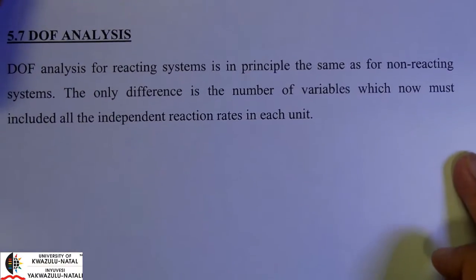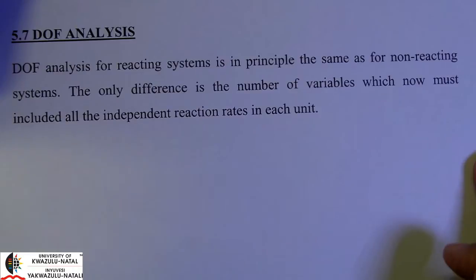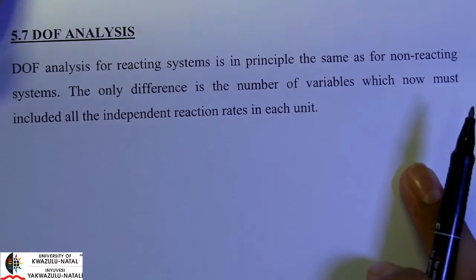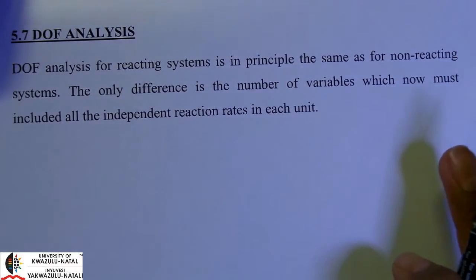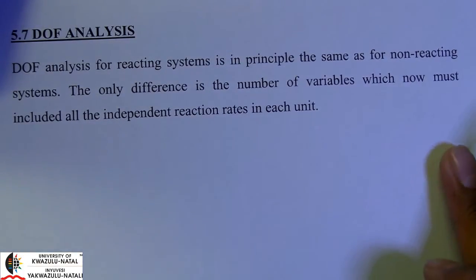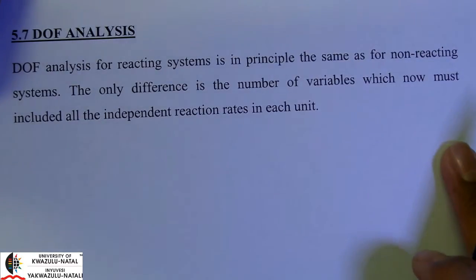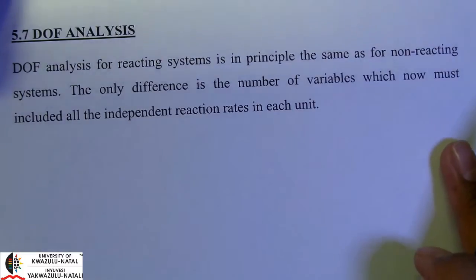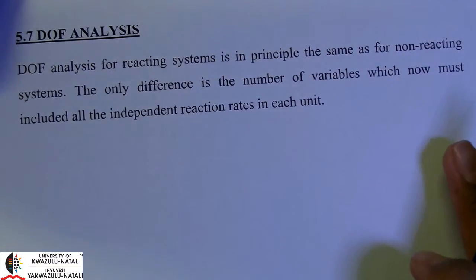One final note, okay, regarding the degree of freedom analysis. Recall that for energy balancing in non-reacting systems, we counted our stream temperatures as well as my heat input, dq/dt, and dw/dt. We've counted those as variables. We've looked at counting a single energy balance for an entire unit, and other information such as the saturation state as subsidiary relations.